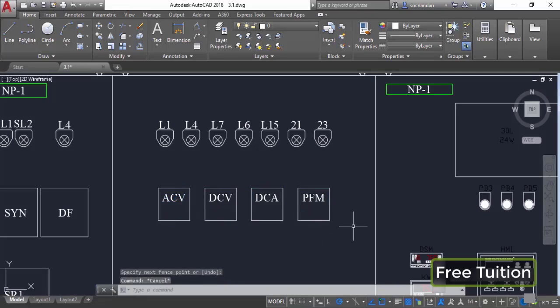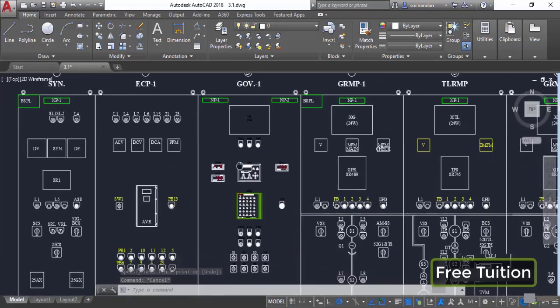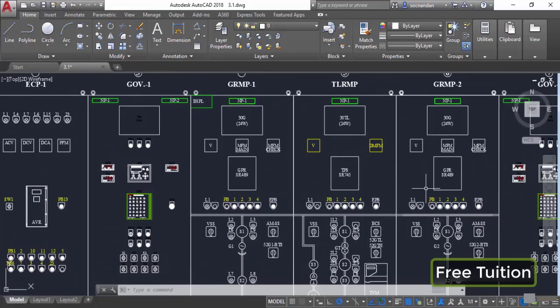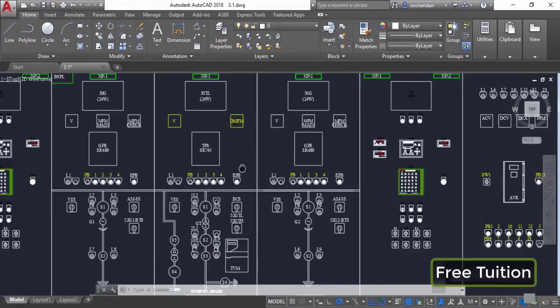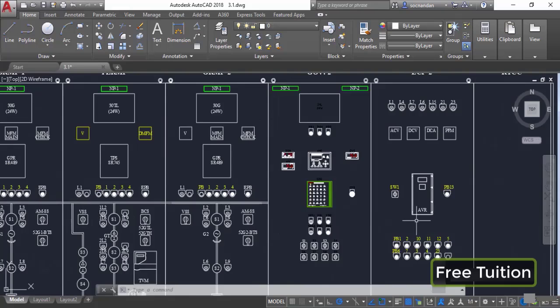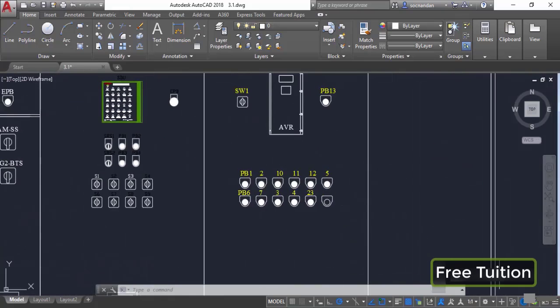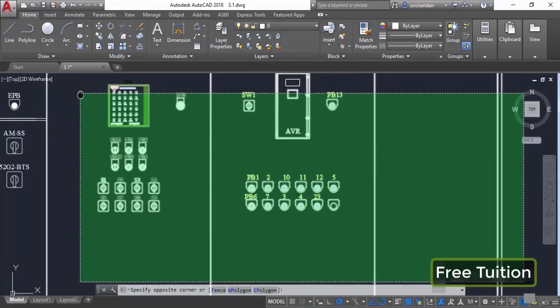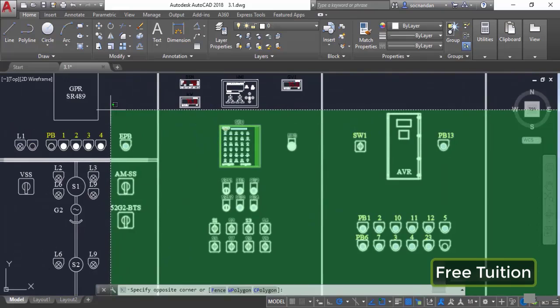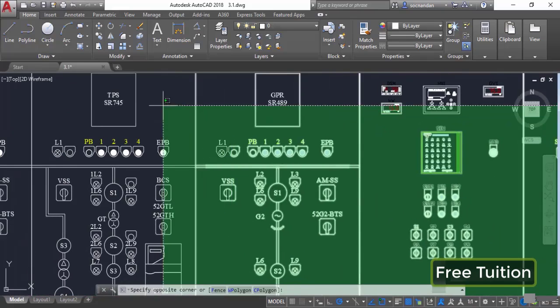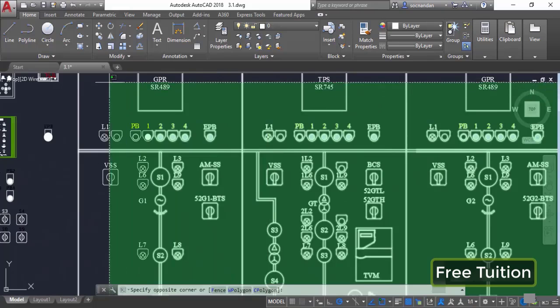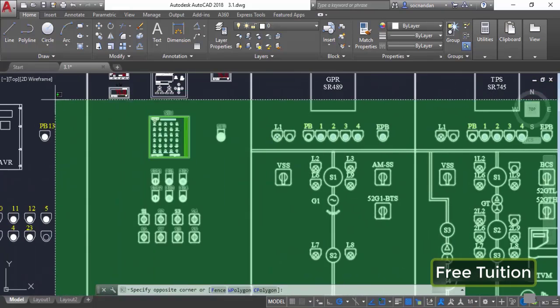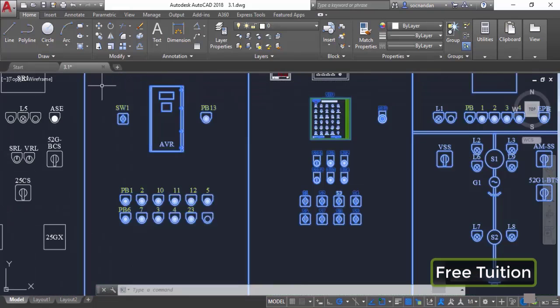In the AutoCAD 2018 version, AutoCAD added an off-screen selection, which is helpful for selecting long geometries. Let's say that we want to make a selection by zooming this drawing, and we just want to start our selection somewhere from here. Now we are including the objects in our selection set, and along with inclusion of objects we are also moving the drawing towards the right. We are scrolling it, panning it here, and now we are including many objects. Now let's click here.